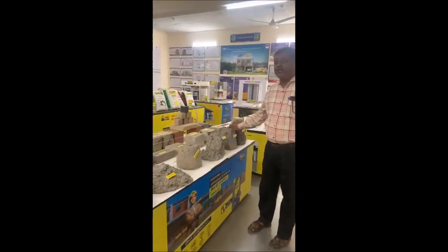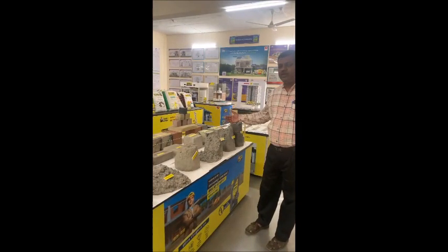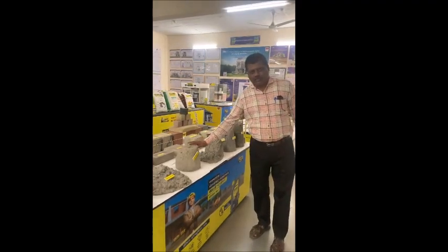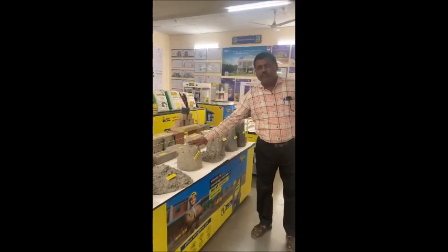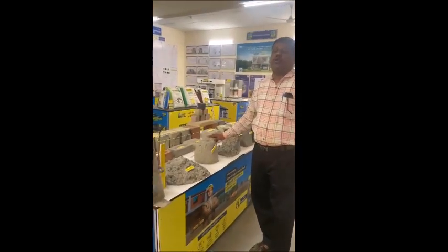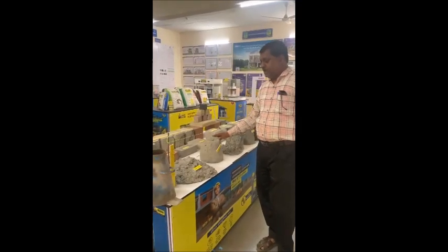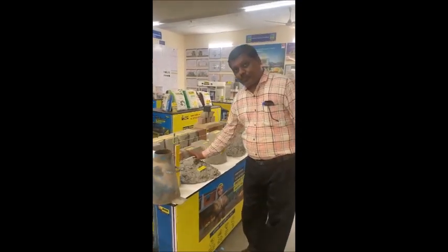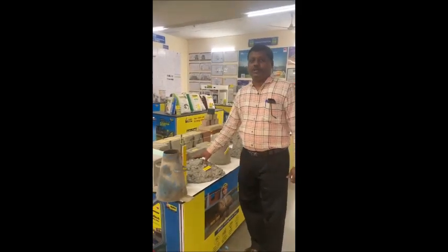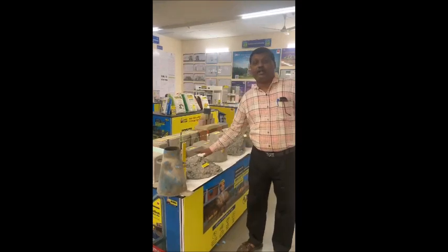Both are not having that much homogeneity. That's why the shear has occurred. You can increase the water cement ratio a little in these two, and you can get the proper true slump, which is shown here. Now this true slump, having 100 workability, is useful for our regular RCC work, meaning our regular building structures, RCC buildings. Now this collapse type of slump is useful for pumpable concrete, especially ready-mix concrete. For that, the collapse type of slump of 180 to 190 value is required.